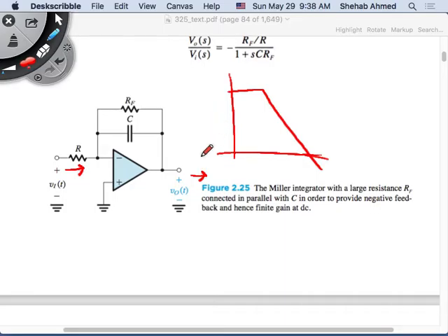not to the full signal, because now unless it's a sine wave, right? Remember I think we did an example where we had several sine waves with different magnitudes and frequencies going through, and we looked at the values of the input and the values of the output. Now I don't have a sine wave coming in, I have a square wave. This square wave is many sine waves. So you cannot just say, okay, I will look at it and I will know what's coming out. If you take this square wave and chop it up into all its constituent sine waves, bring each one of them in, you will know what's going to happen to each one of them at the output.